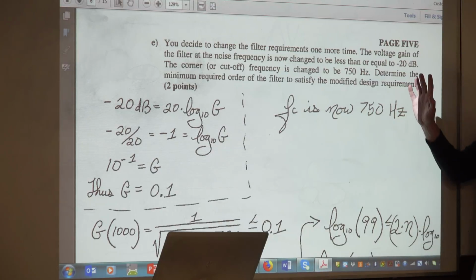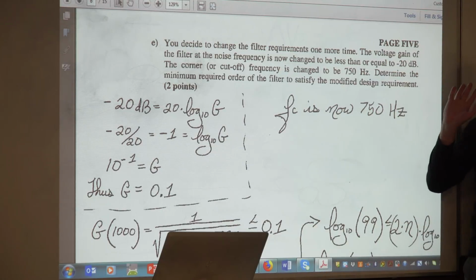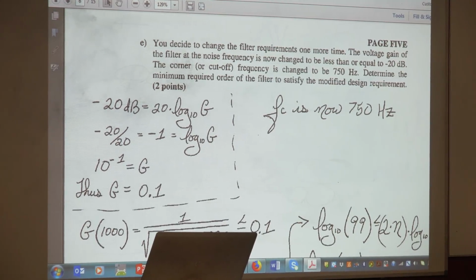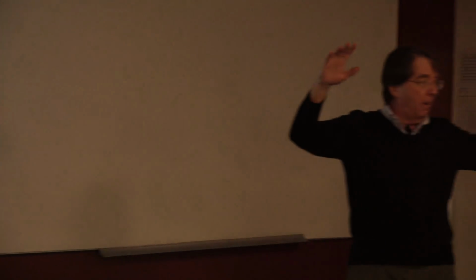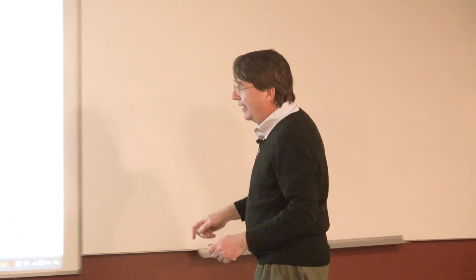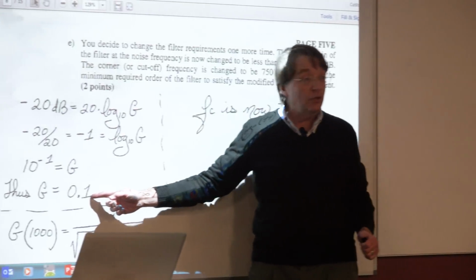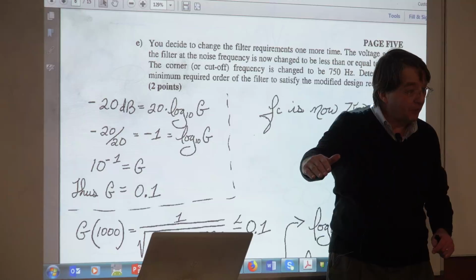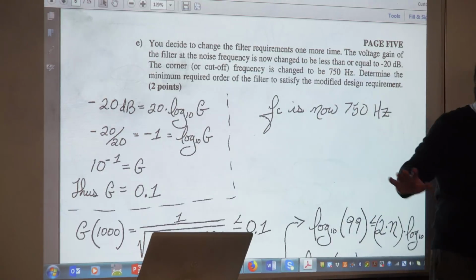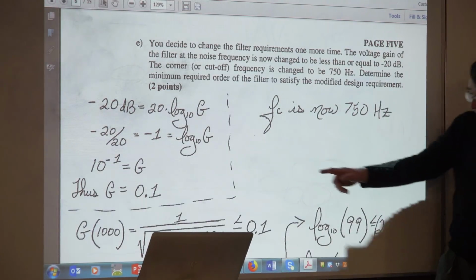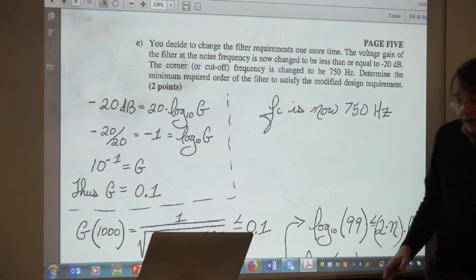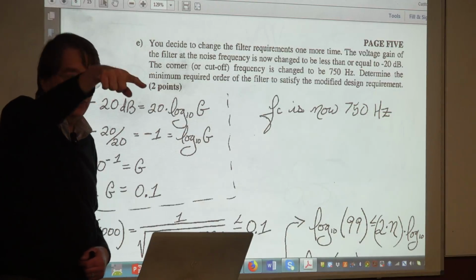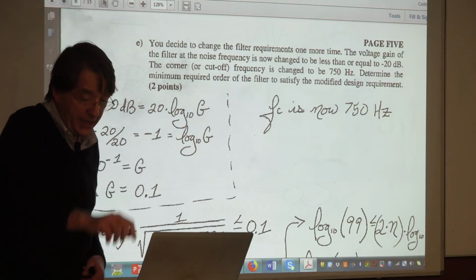Now, how about we go to minus 20 dB? I'm really lowering my standards now. I went from minus 34, 2%, to minus 20, and it turns out that is 10% noise. So I went from 2% to 5%, and I'm saying, the heck with it, 10% is good. So I get that, and I say, okay, what's the order filter? I had 21 or 22, whatever it was. I went down to 14.